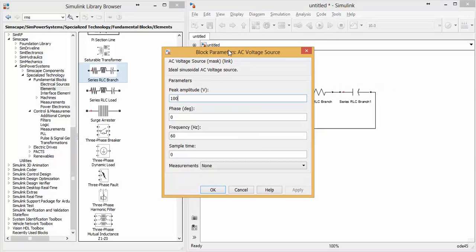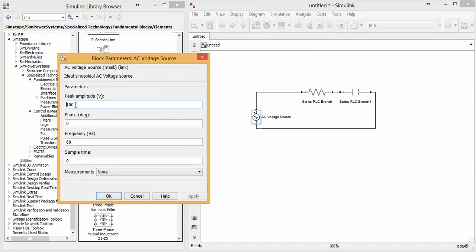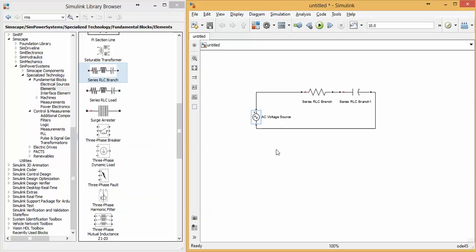Now we need to set the voltage. Suppose we are taking 5 volt with frequency 50 Hz. Actually this frequency we are going to vary, but now our task is to measure the voltage across this power source and this capacitor, because the output is going to be taken from capacitor, across capacitor.